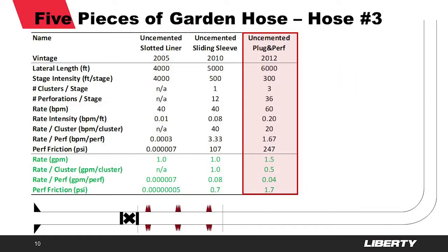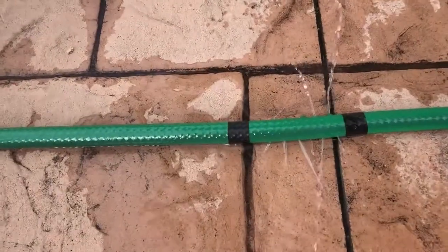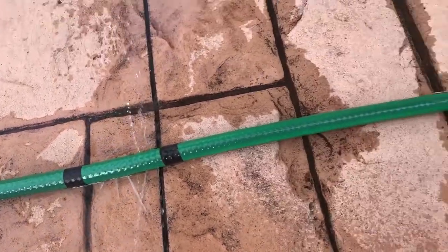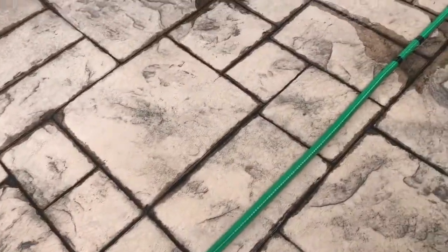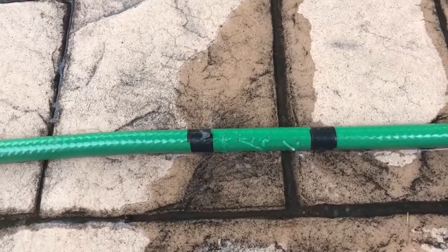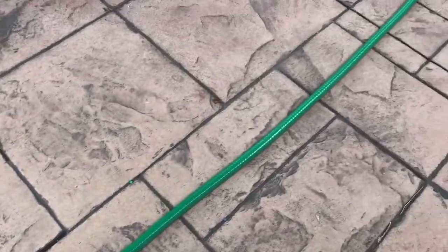Liberty got its start in Williston with well design number 3. The central realization was that more complexity is needed for shale well development. The focus of this strategy was to create complexity through higher rate slickwater jobs in a plug-and-perf well design. Higher rates and perforation clusters encourage control of initiation and create more fractures within a stage and along the well.